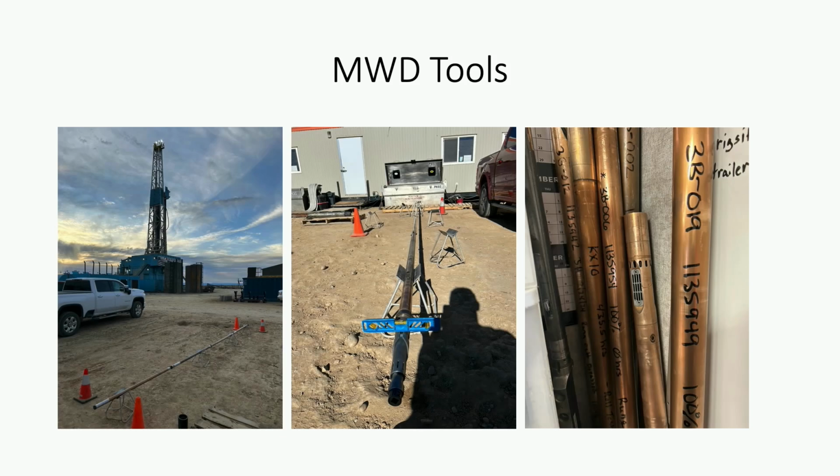On the far left, you can see a picture of what the tool looks like basically without the dipole on it. You can see it comes in sections and it just screws together essentially. And mud's flowing on the outside. Yep, yep. And it just sticks inside of that Monel. And there's a picture of my tools just laying up against the wall. And in the middle picture, I'm high siding the tool to set my zero to match up with the bend of the motor.